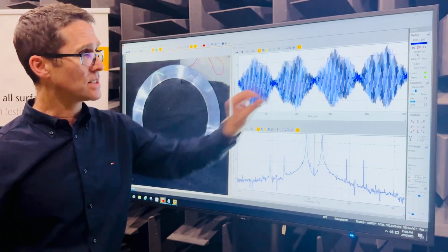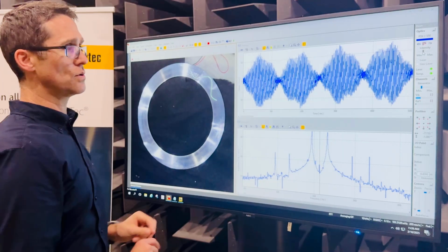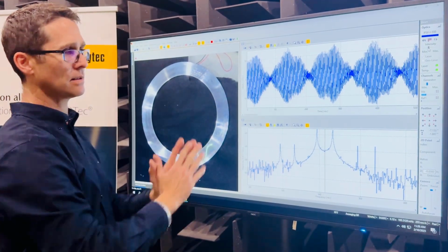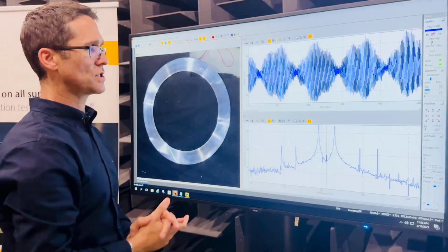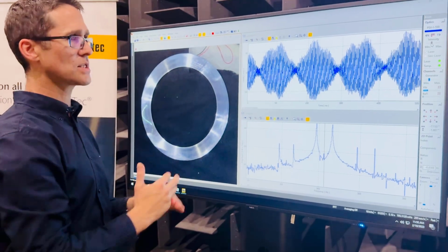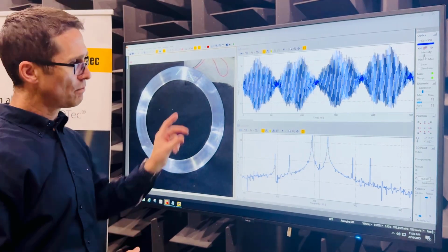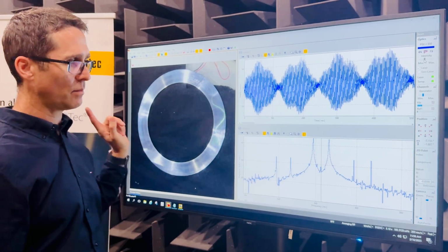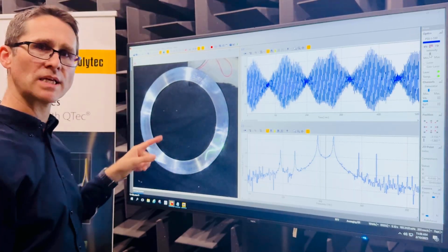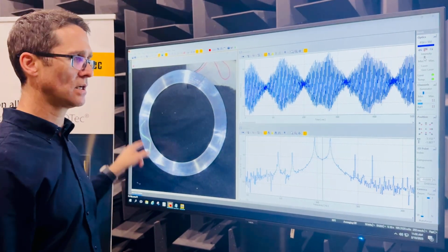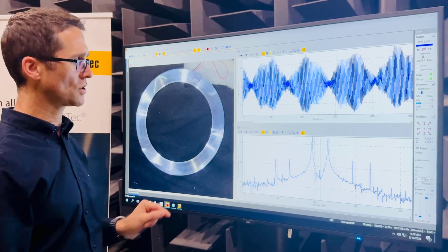These time domain data, however, allow us, in theory, with only 2 seconds of data, that might allow us 10 averages, let's say, or 5 seconds of data if we want to do a little bit more noise suppression, to produce very quickly information about both the resonant frequency and the mode shape, or operational deflection shape, I should say, in this case, of our axisymmetric structure.